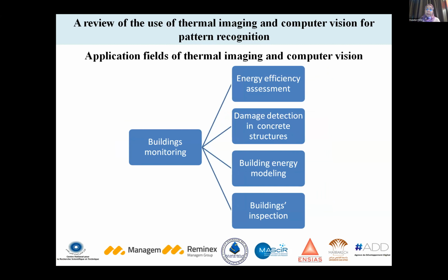Buildings can also be monitored through thermal imaging and computer vision, either for the energy efficiency assessment or for damage detection, especially in concrete structures. In fact, thermal imaging can allow even seeing the internal damage in some components, which cannot be done by human eyes. And we can therefore inspect different aspects of buildings thanks to these approaches.